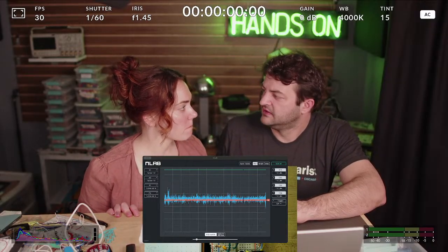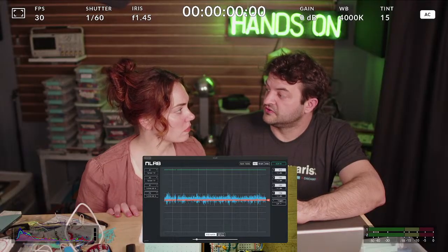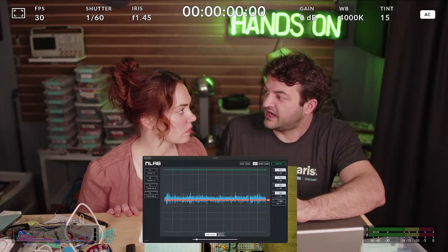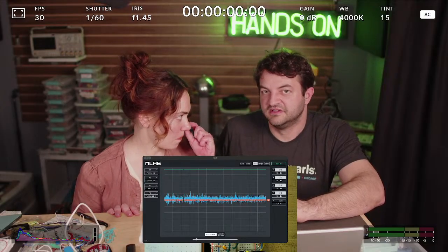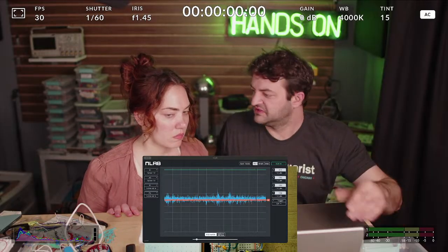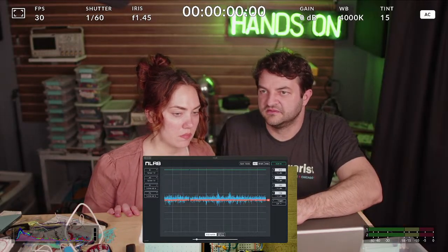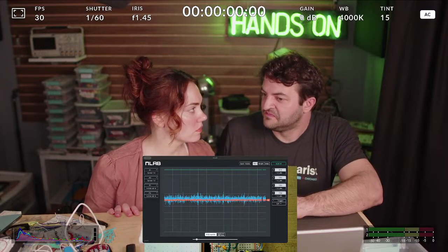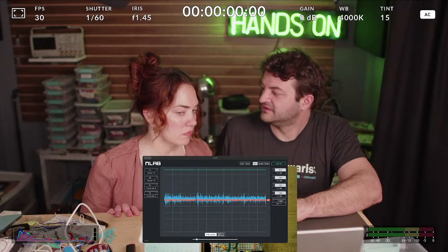So if you're going to build something that goes in a car, usually the temperature rating for all the electronics is larger, because cars can get pretty hot, pretty cold, whereas basic electronics don't get that hot or cold in comparison. Got it. You want to look at, is there a weird temperature range? Is there a weird voltage range? Is it bigger or less than 1 microfarad?